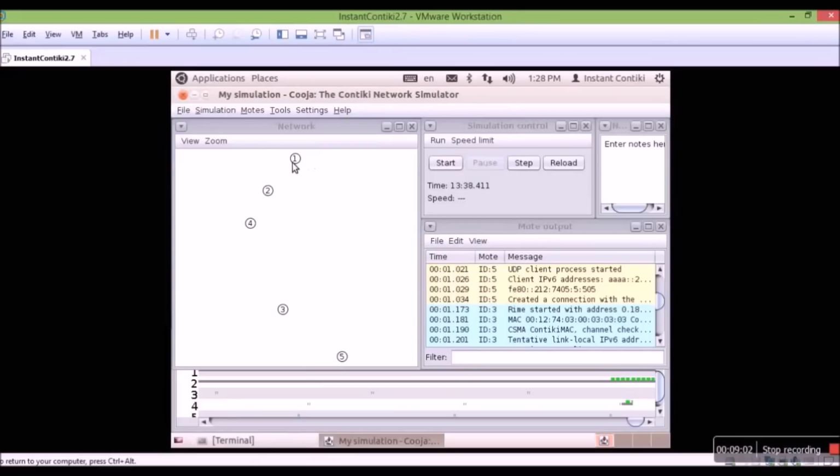Okay, finally we are done with Cooja simulation. We already know that Cooja has many advantages, like it is open source, it has simple UI, flexible, efficient and scalable. It uses basic C, C++ codes. It supports multiple platforms like Z1, SkyMote, etc. It has native TCP/IP support. It supports fully standardized IPv6 and v4. It supports low power standards like 6LoWPAN, RPL, CoAP, etc.